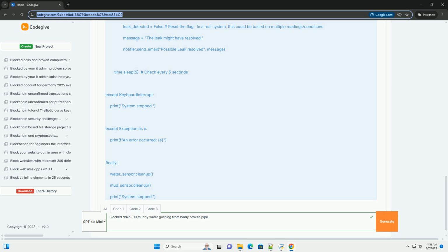2. Initial assessment and damage control. 1. Identify the source. Determine which drain is likely blocked. Is it a toilet, sink, shower, or a main drain line? The location of the leak can help narrow down the source of the problem. Look for obvious signs of the blockage, such as overflowing fixtures or slow drainage. Check clean-out plugs. These are typically located near the base of drain stacks or in basements.